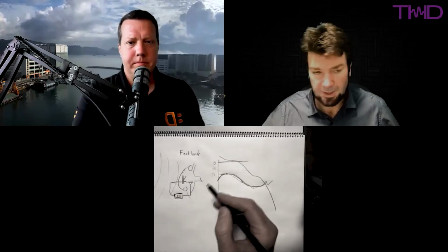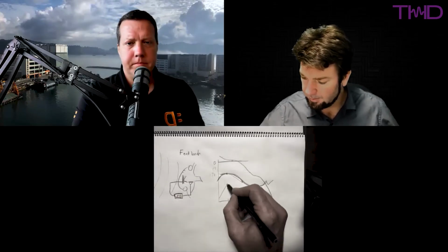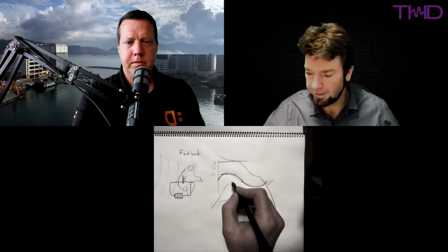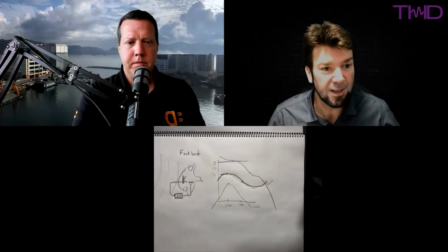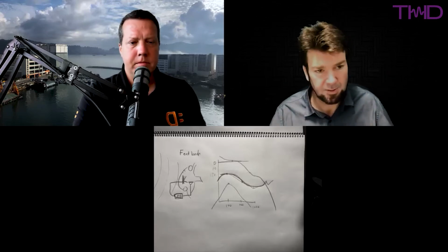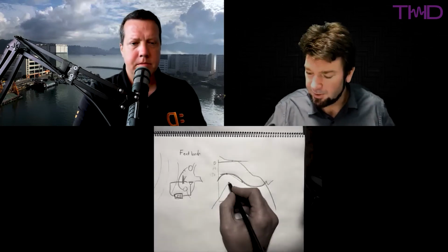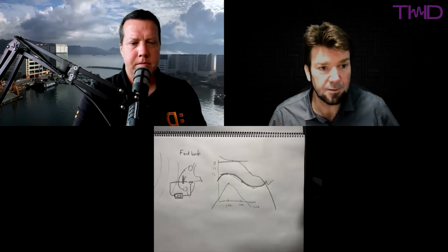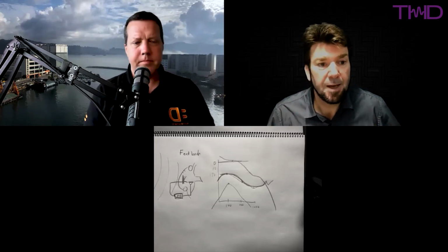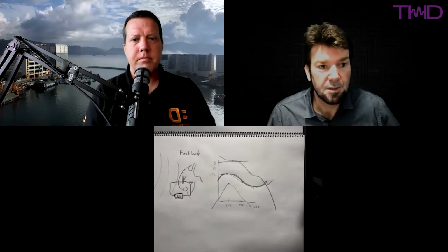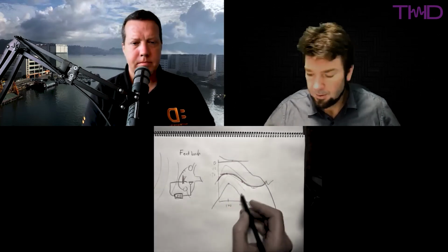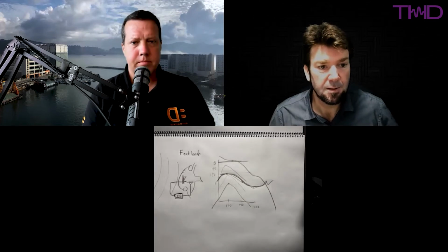In the simple form, you might end up with a filter that does a bump like that. At high frequencies, the gain is way down. At low frequencies, the gain is way down. And at the nice point where the phase is in the place that you want it, you can have your maximum gain of that signal. In feedback, there's no limit to the amount of gain you can put onto it, except that if you keep increasing this gain, at some point you will start having instability.